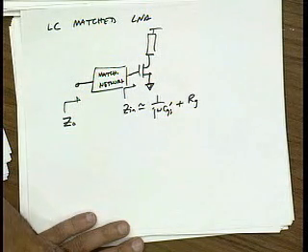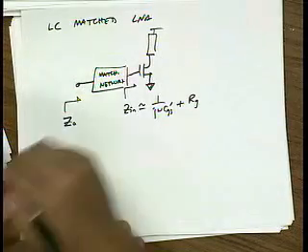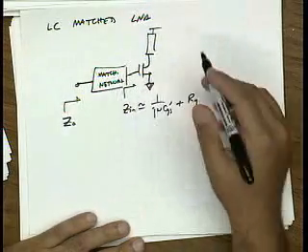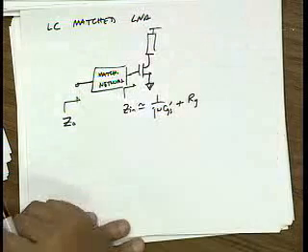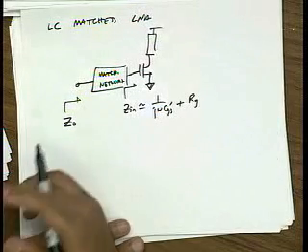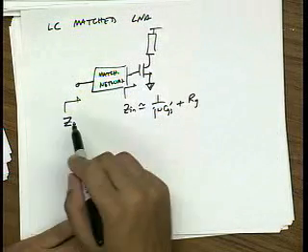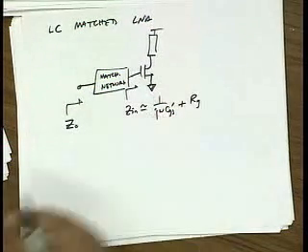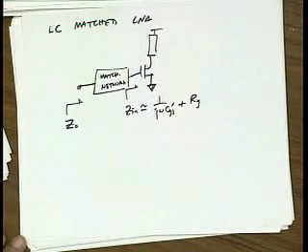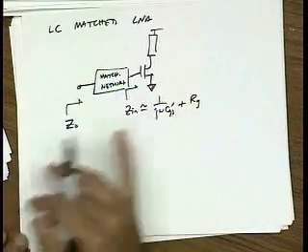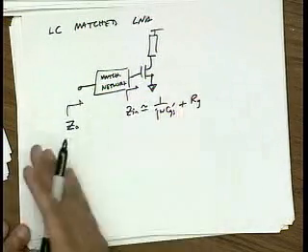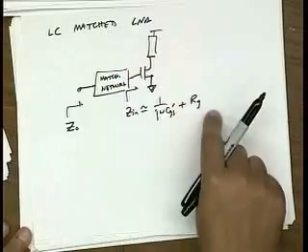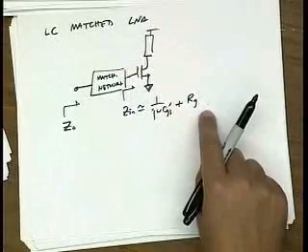Well, the only issue is if you make this a low noise device, RG is going to be pretty small. It's going to be a few ohms, maybe 1 ohm, 2 ohms. And you're trying to match the Z0, which is typically antenna impedances. It might be 75 ohms, 300 ohms, 50 ohms. There's quite a bit of range that you need to go. So you have, let's say, 50 ohms to 1 ohm as one example.